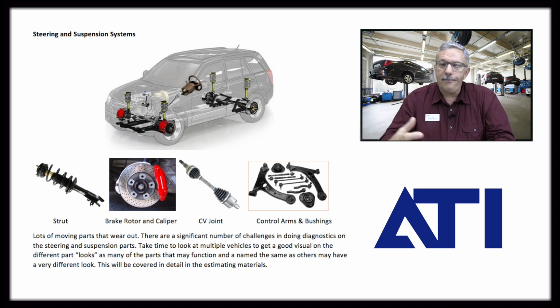Why? We don't want to put the car all back together and actually build in a problem that was a pre-existing issue. So we want to be able to do the proper diagnostics, looking, again, visual inspection of things like the tires, looking at, what's the movement of the ball joint? Is it difficult to move? Is it easy to move? Is there stress in it? Is there not stress in it?